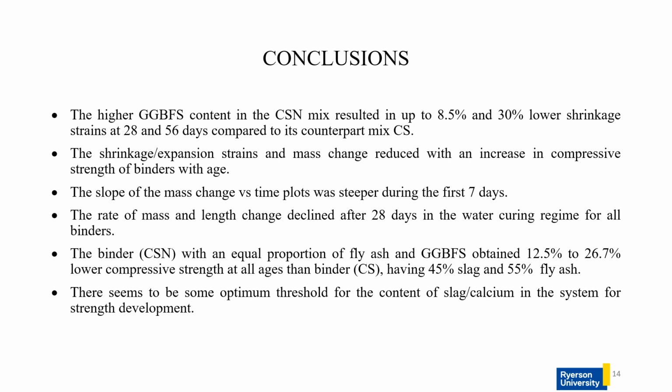The slope of mass change versus time plots was steeper during the first 7 days, indicating the rapid geopolymerization or the cementitious reaction. The rate of mass and length change declined after 28 days in the water curing regime for all binders, indicating the completion of geopolymerization or cementitious reactions.